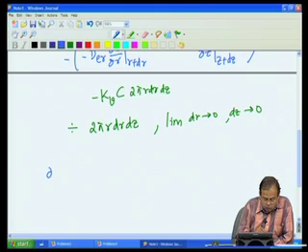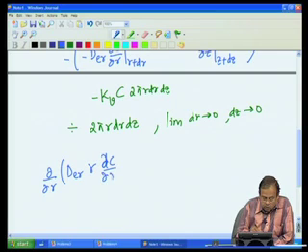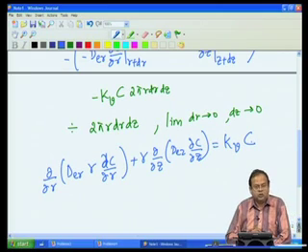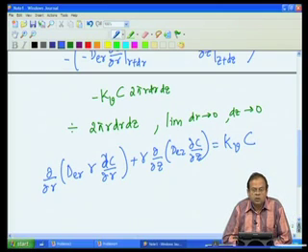the following: ∂/∂r of (De r ∂C/∂r) plus r ∂/∂z of (De ∂C/∂z) equal to kV into C. This is our mass transfer equation. So, this is our mole balance.